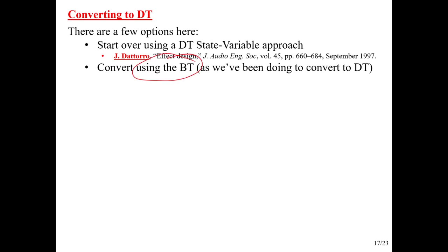Use the bilinear transform. Yeah, the problem with that is that it might not retain all that nice characteristics of decoupled control and 4 separate outputs and things like that. So it's a little bit of a risk doing that. I've not done it, but my guess is that since nobody else has done it, or at least published it, my guess is that it doesn't work.